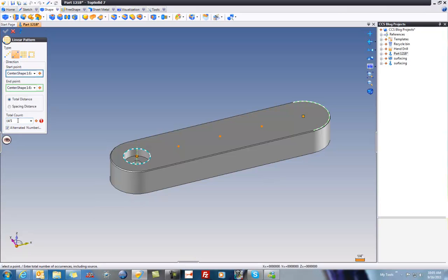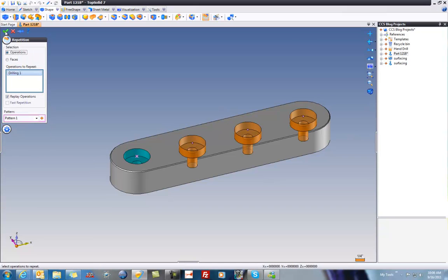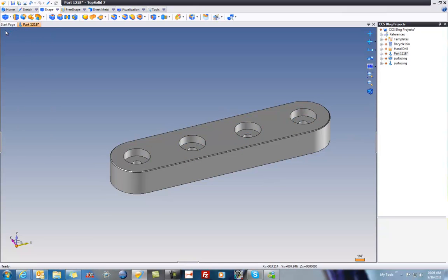divided by 1, and I'm going to put the unit of inch there, and then I'm going to say minus 1. By dividing by 1 inch, that crosses out the unit, and then I can subtract the unitless value by this value. Perfect. We'll say OK, and we'll validate. So now we have 4 instances.